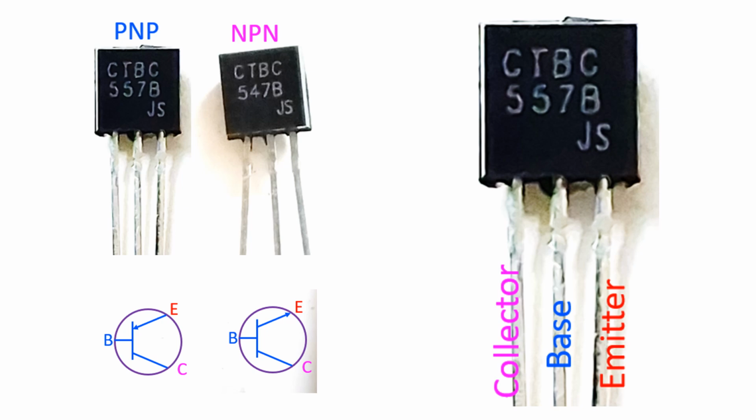Terminals of BJT are named base, collector and emitter. Current at the base terminal, which flows between the base and emitter, can control or switch a much larger current between the collector and emitter. That is how BJTs are used for amplification and switching.